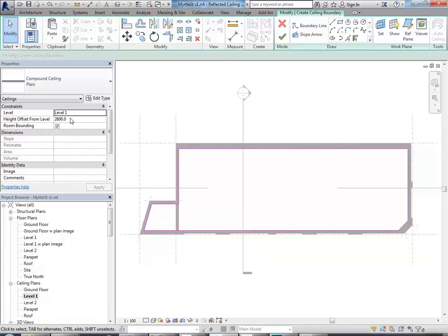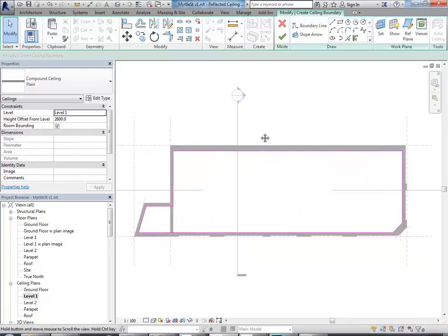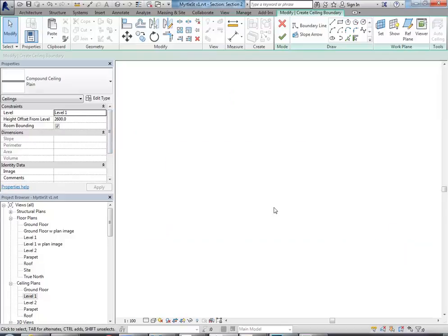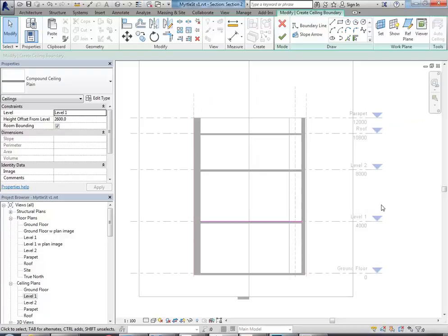now I'm going to set the height, and that's probably the thing people have the most issue with when you're making a ceiling. You can either set the height using a level, so you'll see some people will make a level for each ceiling that sits just below each floor level. That's one approach. But I think for a building this simple, you don't need that. It's much easier just to have a level for each floor. And that's generally a good approach with Revit.